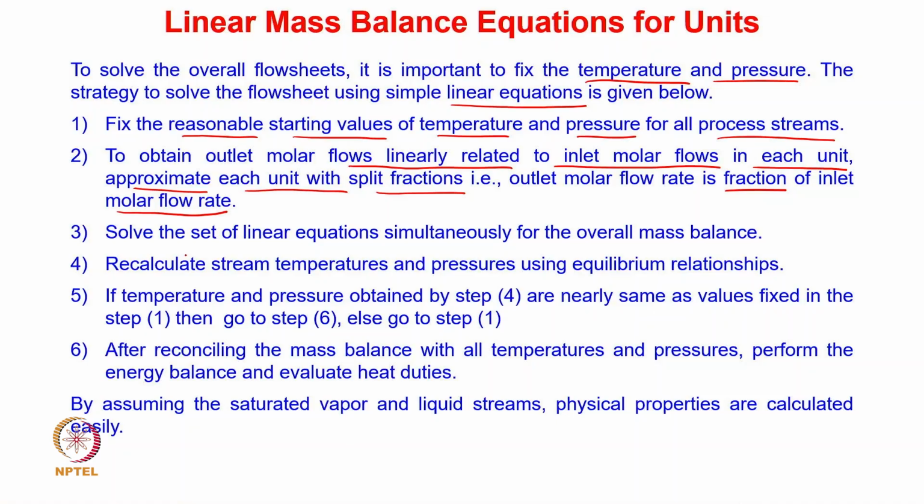The third step is, all this set of linear equations which we have obtained for all the units, we solve these linear equations simultaneously for the overall mass balance. Once this overall mass balance is done, then we recalculate. The next step is, we recalculate the stream temperature and pressures using the equilibrium relations, and then we cross check